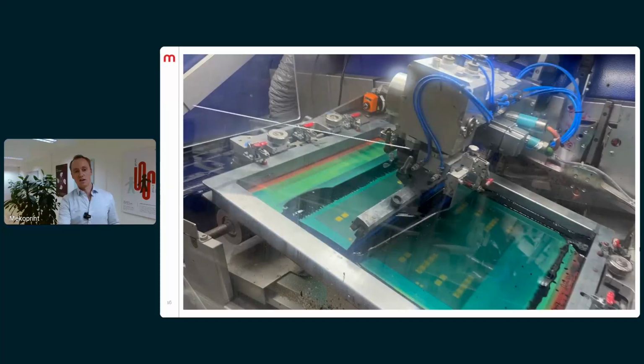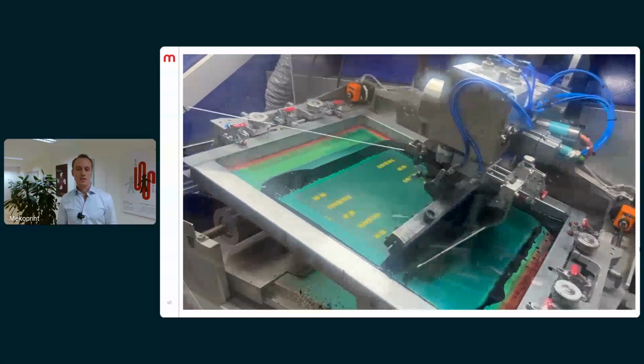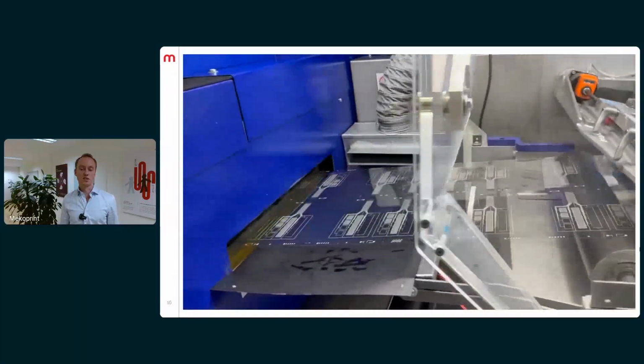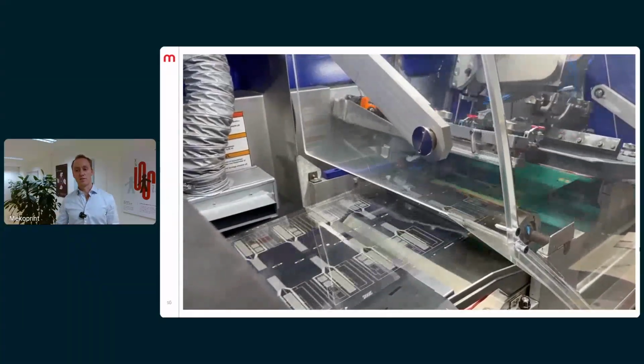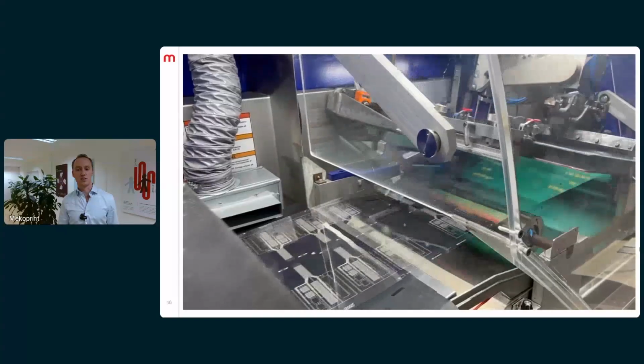So then after it's been cured, it comes out the next printing section. So here the second print is a transparent cutting layer that's printed onto the silver that was printed first. So we position this print based on some register marks made in the first print, so all following layers are perfectly aligned to each other.